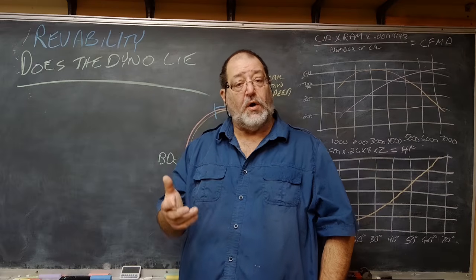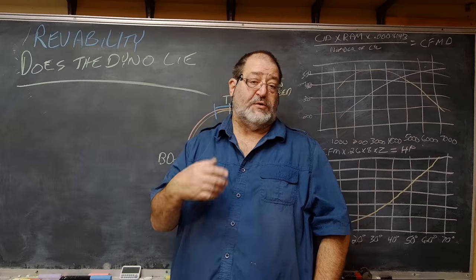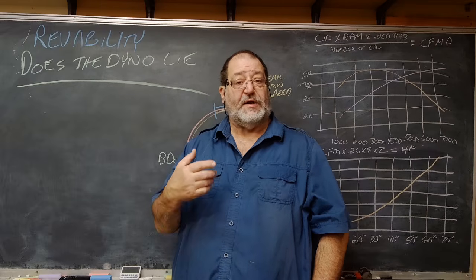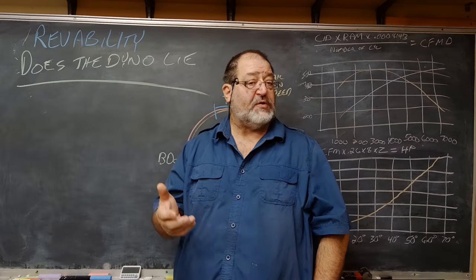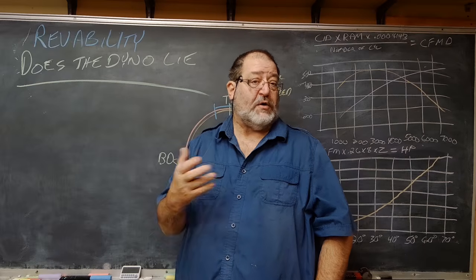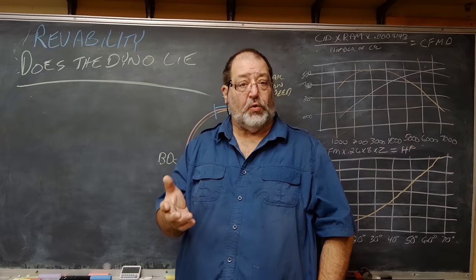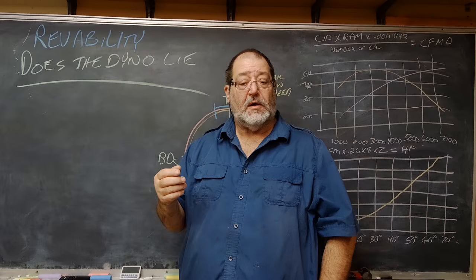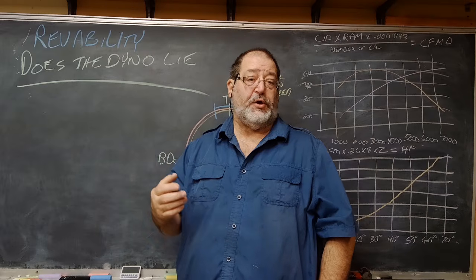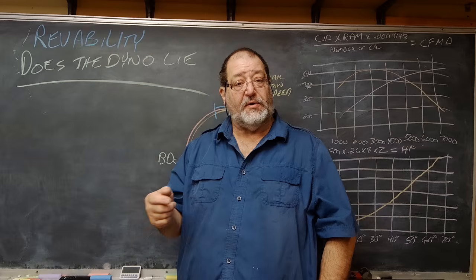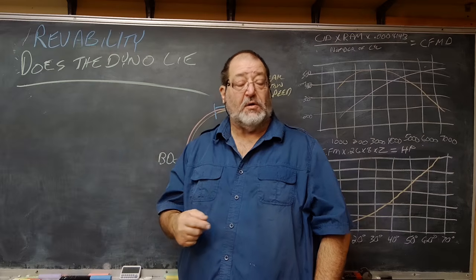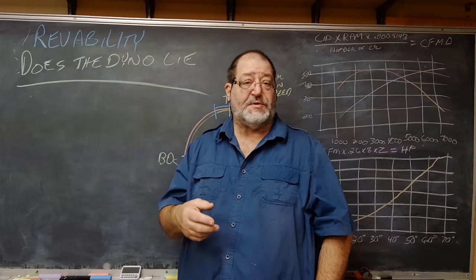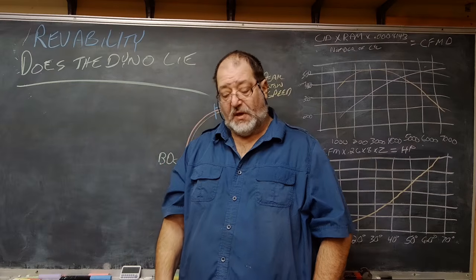I've told you before, especially for driving characteristics and how well a street engine is going to behave, the dyno's not a good tool for that, unless you go to a hub dyno where you can adjust the load, make it more like driven while you're looking at the parameters and can tweak the engine.